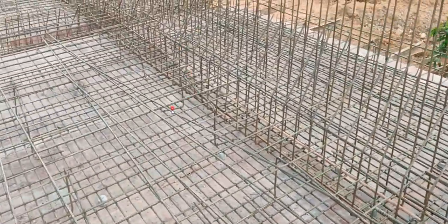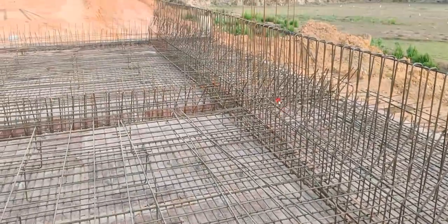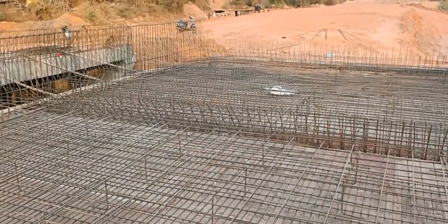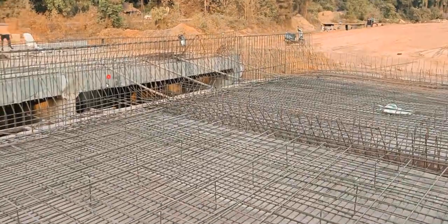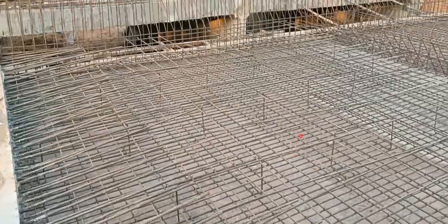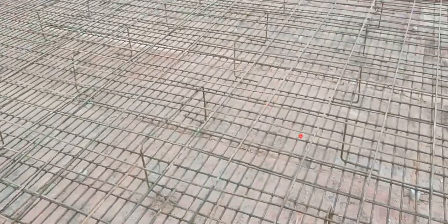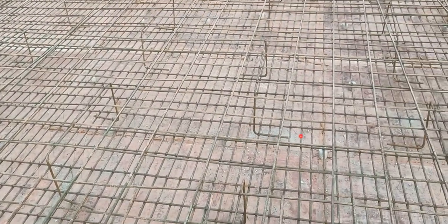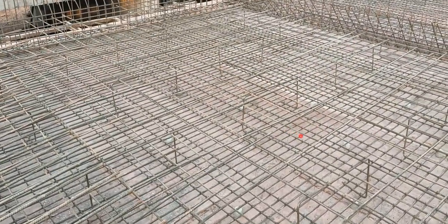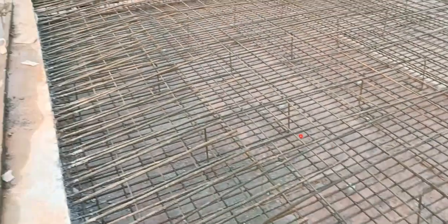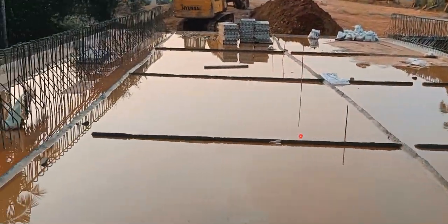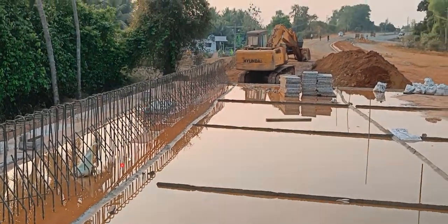This is for crash barrier. Okay, this much portion is my crash barrier. So along with this top slab, this crash barrier also will be casted. This reinforcement will be casted along with the top slab. So it's very simple. The reinforcement is, we'll get a bottom mesh and we'll get a top mesh. Simple. Okay, like we did for the combined footing, for the raft and all, the same thing you have to follow here. And here already the curing is happening. Okay, everything, this is your crash barrier part.